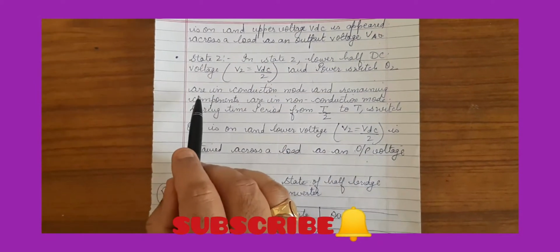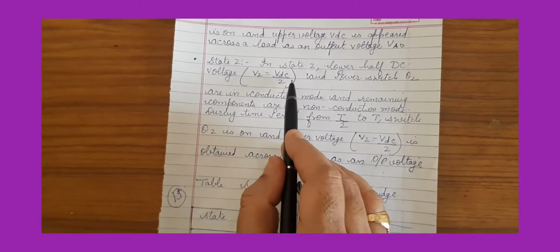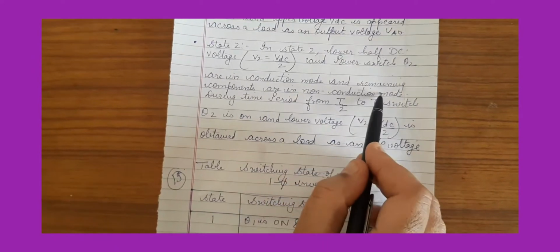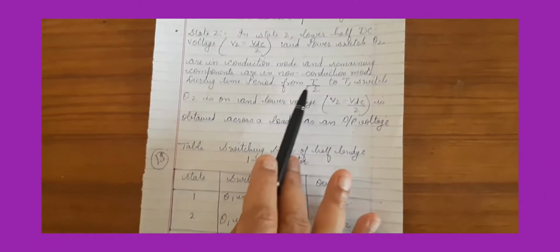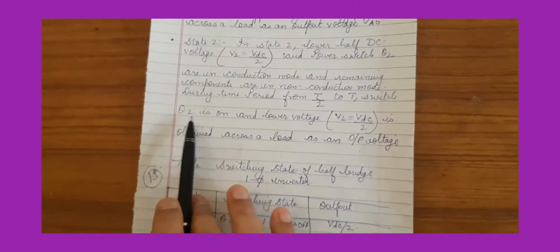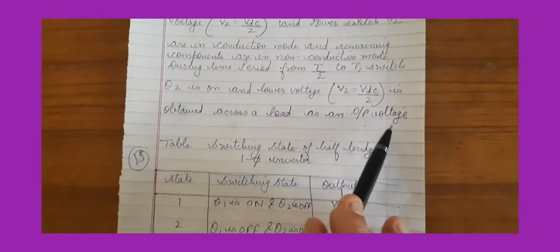Now in stage 2, the lower half DC voltage V2 is equal to VDC upon 2, and power switch Q2 is in conduction mode and the remaining components are in non-conduction mode. The time period of stage 2 is from T/2 to T. Switch Q2 is on and the lower voltage is obtained across the load as the output voltage.